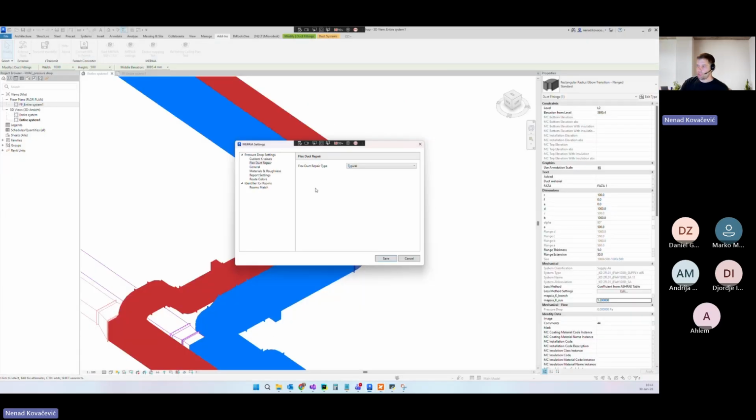Generally in the calculation, you will have 1 flexible duct in the critical path. So even if you say do not use it, or we have good conditions on the construction site, okay, I can respect that, but we just want to improve it a little bit and to foresee actual problems which you will have during the construction. Over here, of course, for ducts and also for the flexible ducts, you can choose if you want to use the first, second, or third option for the equation. By default, because it's the most accurate, we will go with the Colebrook equation, but you can change it.